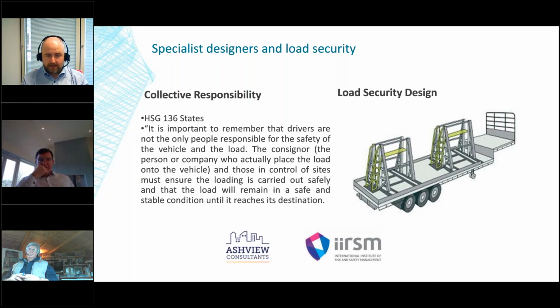So again, it's about early engagement. When the precast designer is designing these panels, there's no point in designing a panel at 17 or 18 ton that can't be transported. So he needs to design these panels for safe transport. The A-frames and the type of products used to transport the panels obviously need to be designed. The design of the frames, the safe working load, the safe strapping of them, what type of trailers, sometimes maybe needs a step trailer, a panel trailer.